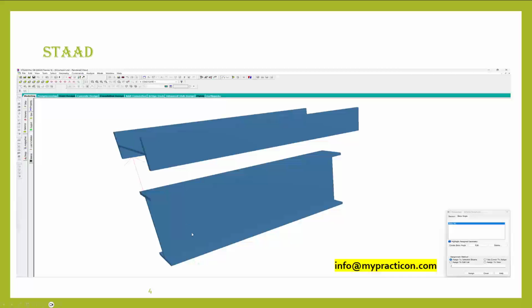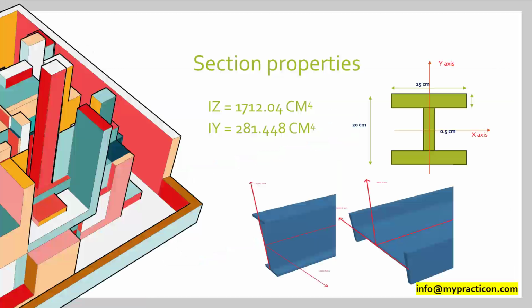So let's say you have a column, beam members, or bracing members, and you want to orient those sections at 0 degrees, 45 degrees, or 90 degrees. You can use this beta angle to orient in that direction. When you make this change, with members oriented with respect to the forces, how does the STAAD engine consider this?